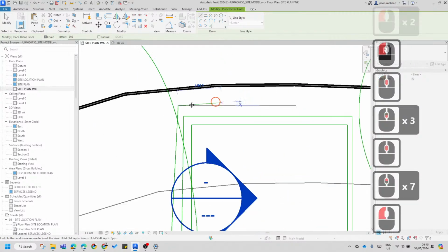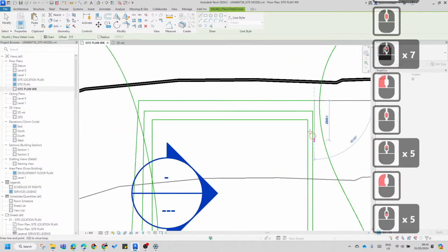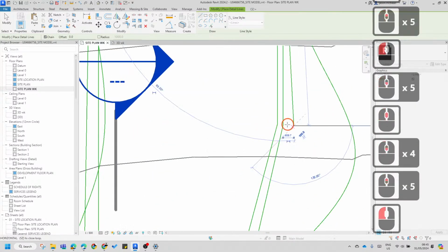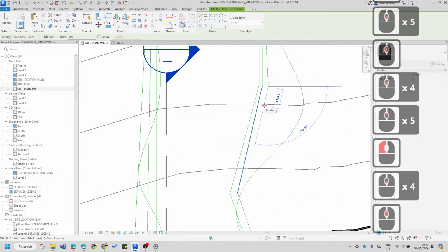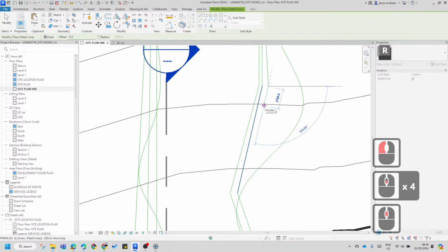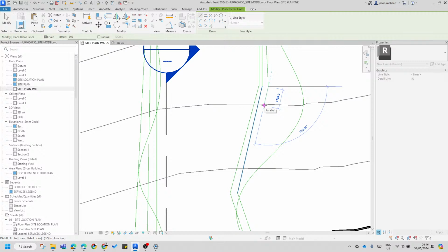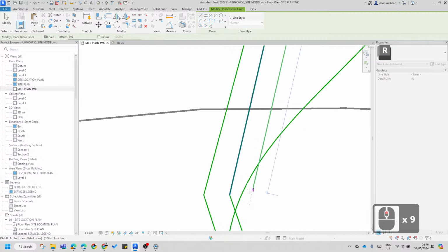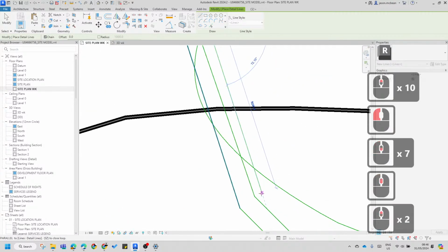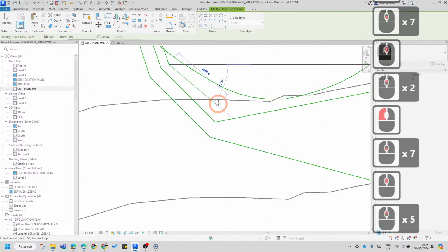And you can move these points closer once you need to. And I'll explain what we're doing now, in the sense that when you create an embankment, it's very difficult to create a perfect embankment in Revit. So you just need to offset the lines a fraction, but you're going to build a retaining wall there in any case, which you can use to cut away. So it'll look perfect. So don't worry about it. Now, if you need to add points, I'll show you how to do that as well, to refine.